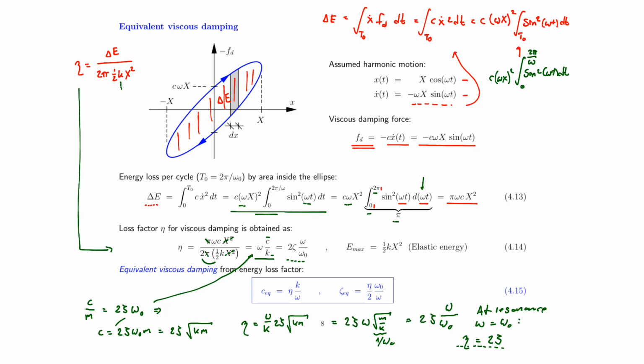So let's assume that we revert our solution for the loss factor so we can actually identify a viscous parameter. Because in many cases, you would obtain the loss factor from experiments, numerical solutions, or knowledge of other damping mechanisms that you want to transform into a viscous parameter.